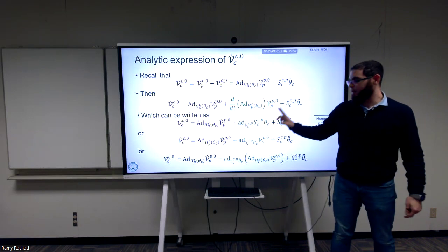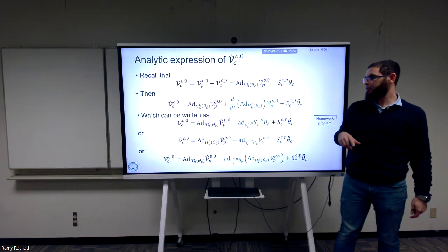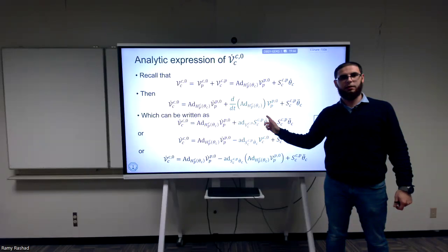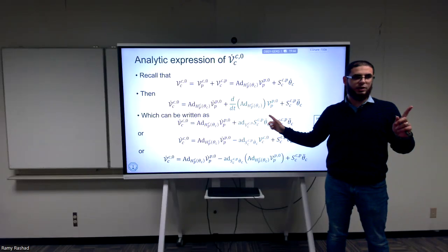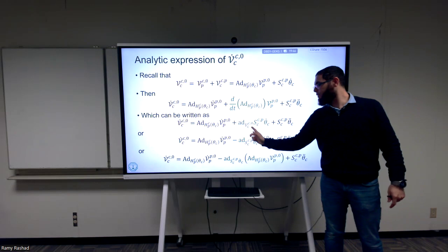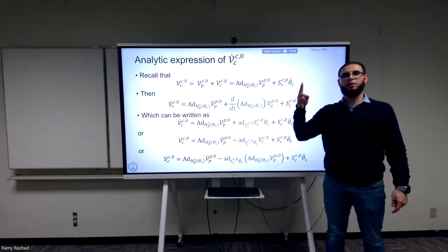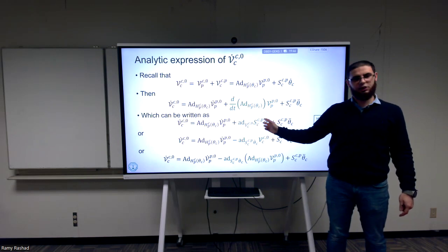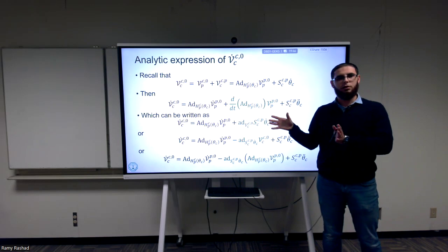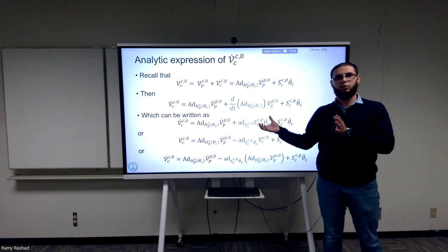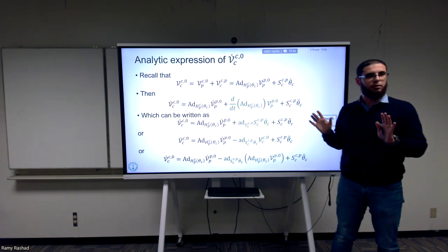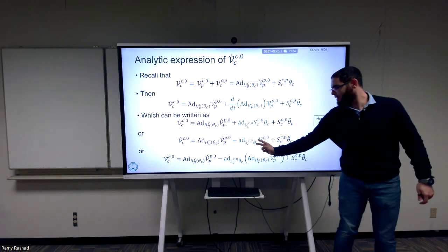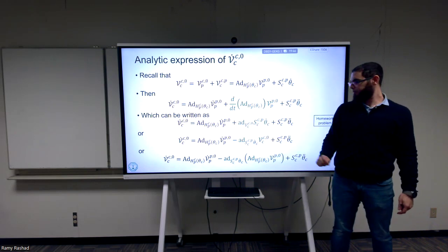I can also, the adjoint has a very nice property. You remember last time when we said that the adjoint of some twist with respect to itself is equal to 0. If you have the adjoint of V1 with respect to V2, and you swap the order of 1 and 2, what happens? You get a minus sign, okay? Because this is just a property of the adjoint. It's actually a general property because this is just one way of writing what's known as a Lie bracket. So if you ever heard the term Lie bracket, this is something related to it. So when we swap these two together, we get a minus sign from outside. So this is just what happened.